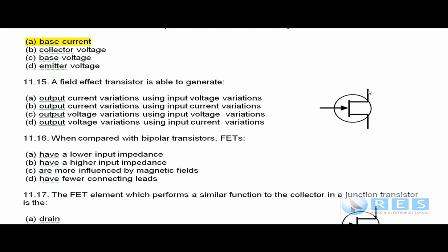Gate, drain, source. The difference between a field effect transistor and a bipolar junction transistor: in a bipolar junction transistor, it's changes of base emitter current that control the much larger emitter collector current. With a FET, it's not changes of current that does the amplification, it's changes of voltage on the gate that control the much larger source drain current. So it is an amplifier as well.